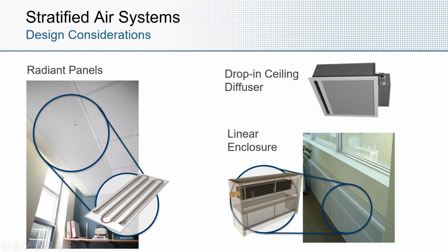Or you can have a ceiling radiant panel to provide heating in the space, or pretty much all of the displacement products come with a heat-cool switchover option. So in heating mode, we'll have this mounted in the ceiling for this particular product, and that will operate and throw across or directly downwards from the slide diffuser and essentially mix up the space in heating mode.